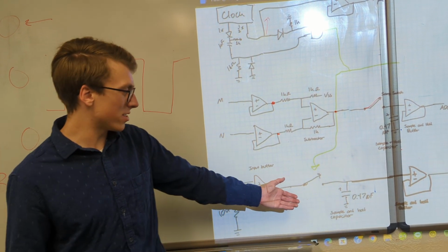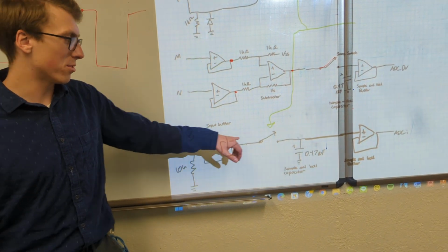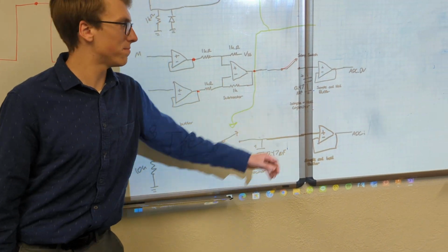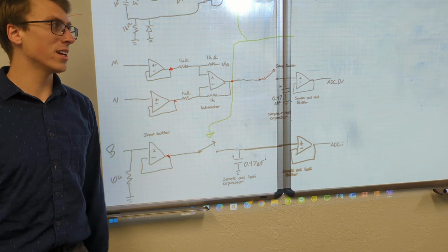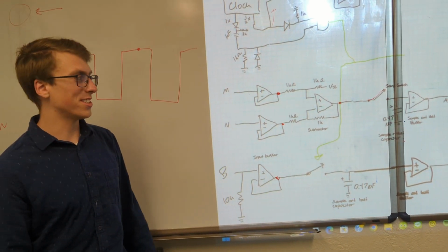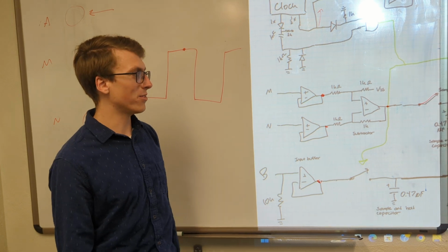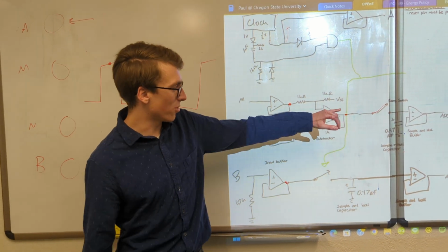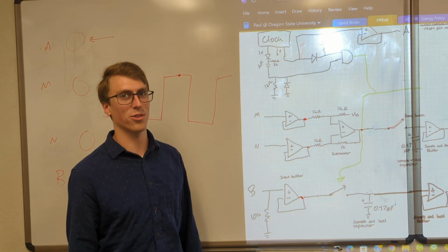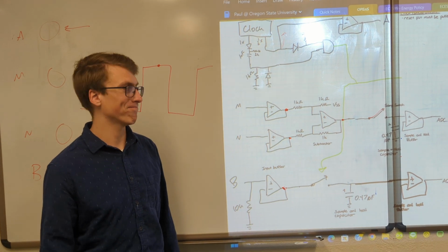The same circuit is present on the current measurement side, where we have a switch, we have a sampling capacitor, and then we have a unity gain buffer. Everything after the unity gain buffers is the ADS1115, this standard 16-bit ADC that we use for pretty much everything else. And this whole circuit takes 2 inputs of the ADC, leaving 2 remaining inputs for other purposes. All right.